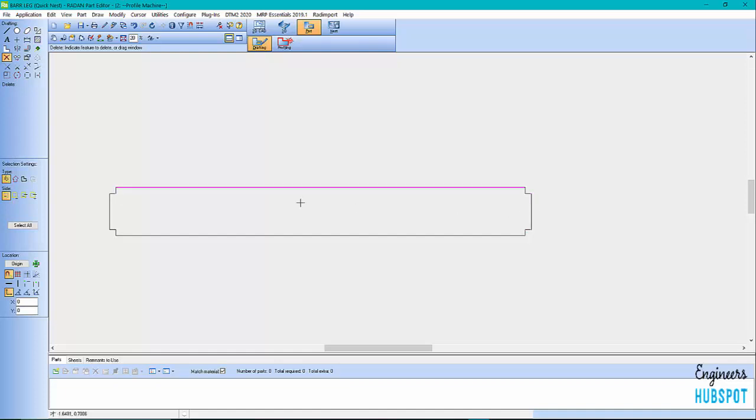On this bar sink, I'm probably going to bend this up, right? So from here I'm probably going to bend this, come in 12 inches, right? And remember I've got a half inch here, so I'm just going to do an offset.